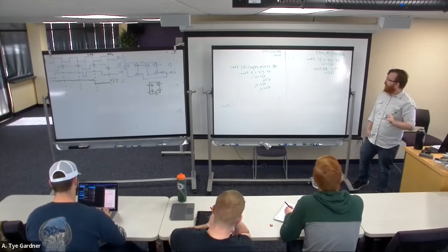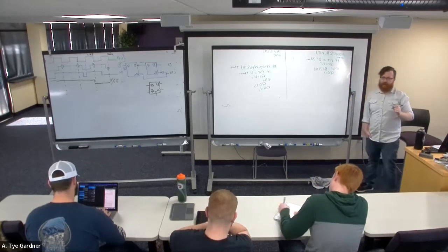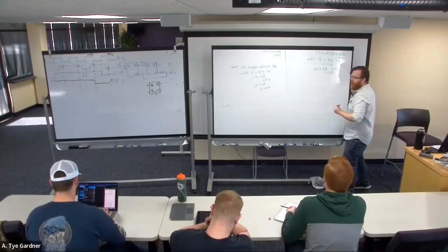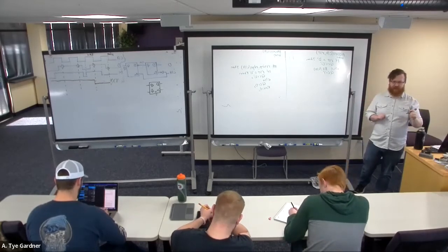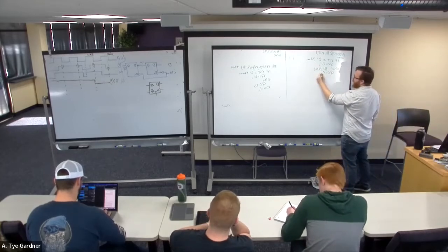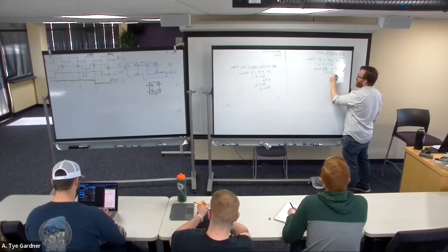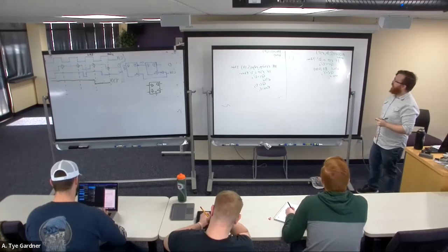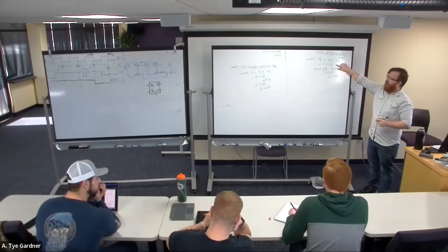You should say begin at the top. It should say begin. My VHDL on the whiteboard is never going to be perfect. I don't have a checker for me, right? And it's really easy to forget. Like I forgot the apostrophes here, right? We need the apostrophes if it's a bit, and we need quotations if it's a vector. Else if, right, and I forgot the semicolon, something like that. If rising edge of clock, and RE is rising edge as written there. There we go. That is an asynchronous reset because the process will react to the change in reset and do the reset.